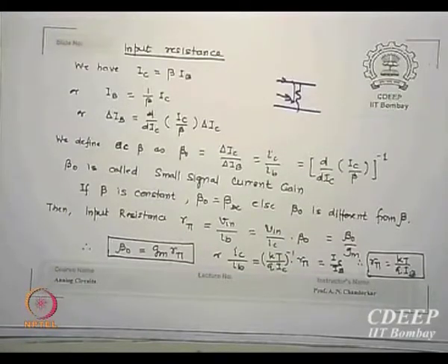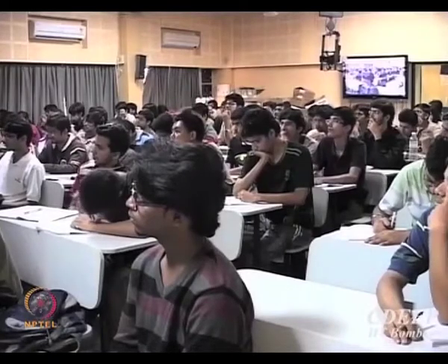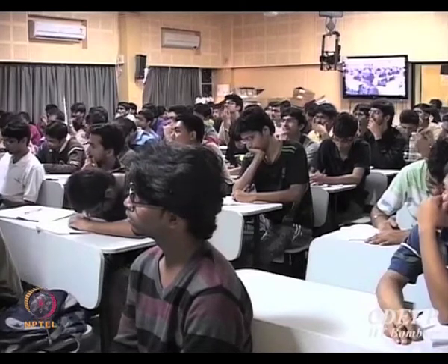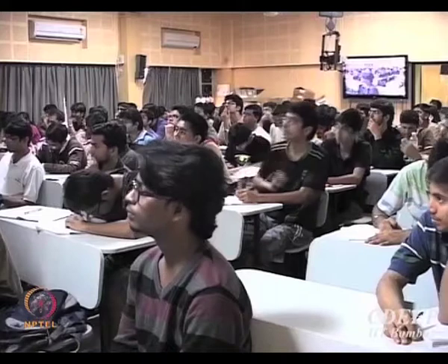So where should you therefore operate? In those IC regions where beta roughly remains constant, you can use DC beta as the same as AC beta. Therefore the DC biasing is again very important, because I don't want to always separate DC and AC beta. Is that clear? So I am giving you why we operate only this much, because otherwise we are not sure what values we are actually going to get. Is that point clear?